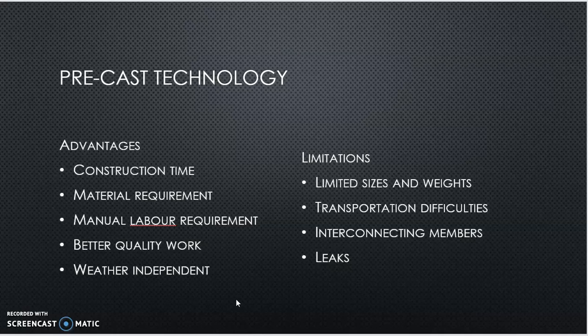The limitations. Of course, everything has limitations also. Since you're going to use something which is factory casted or casted separately, there will be a limitation on the sizes. You will have to decide on the sizes which are available. You can compare it to clothes which you get stitched from a tailor versus ready-made garments. There will be a limitation. Casting in situ on the site is something like a tailor-made job.